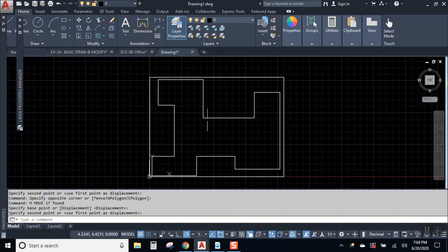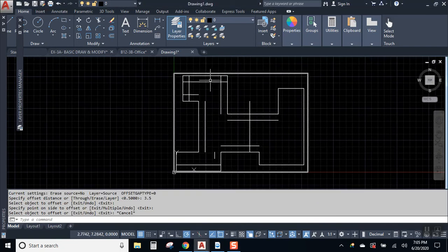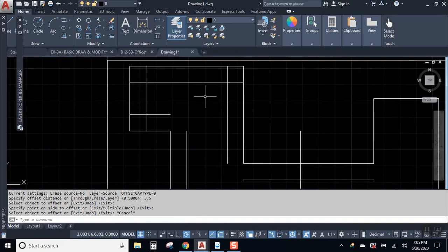Okay, and we're starting it off with the corner square. Well, if you do this, the next several steps are not that bad. Okay, I'm going to start by making my inside line work, and I'm not going to draw lines to do it. I'm going to use a command that basically makes a copy of one line a certain distance away from the other lines. Alright, and there's all my lines copied a ½ inch away. And you can use the copy command, you can use the offset command. Those are the only really easy ways to do this.